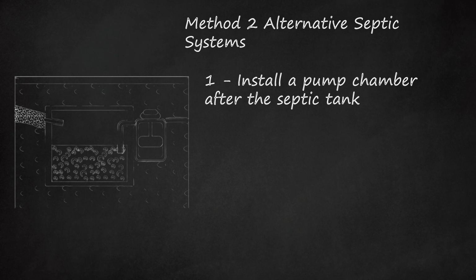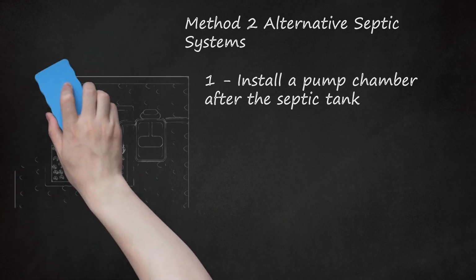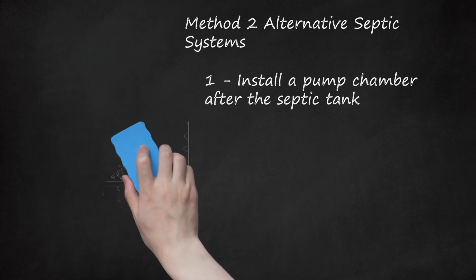In areas with high groundwater, be aware that the pump chamber or additional ATUs may be mostly empty much of the time, and these tanks may have to be protected against flotation by the use of extra weight or other protective structures.